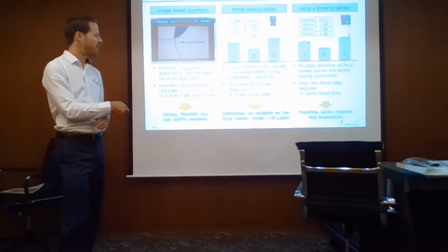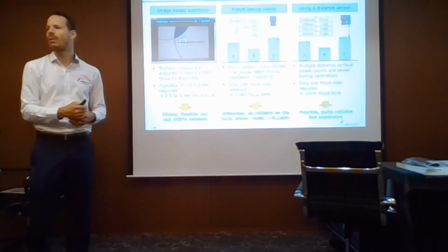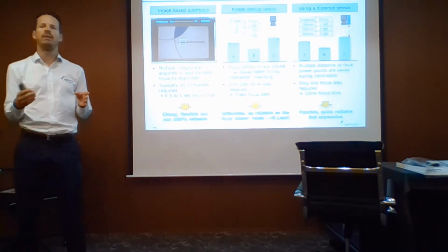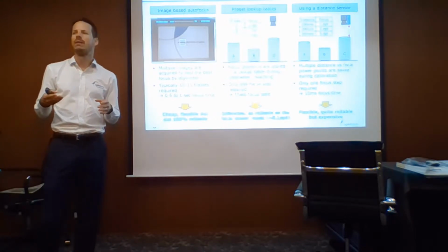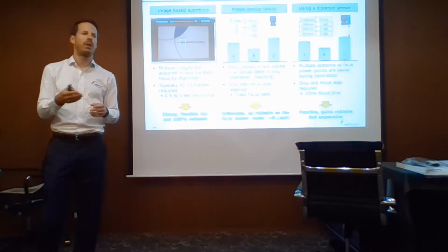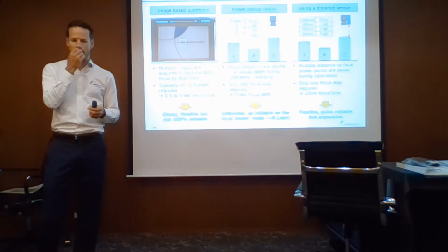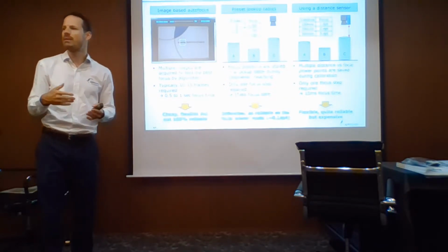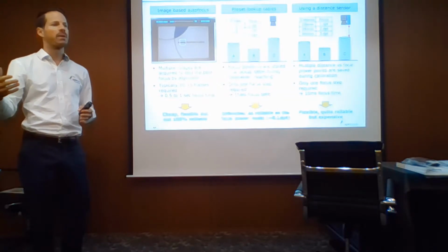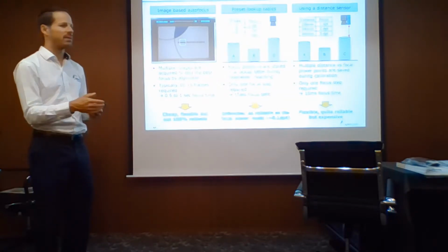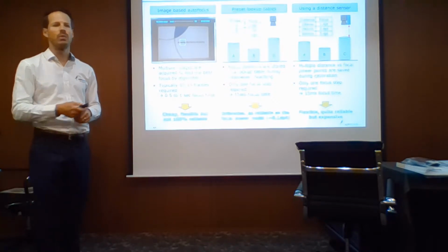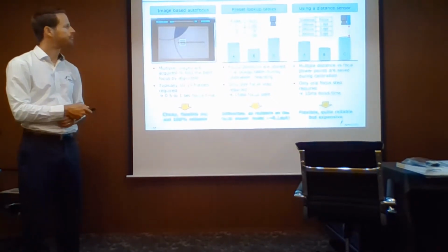So roughly 15 milliseconds, you can jump to the right position. But we then have to offer the high repeatability. So this calibration has to remain working for maybe several months or years. That's why we definitely need this temperature compensation, to make sure that we don't lose the calibration.